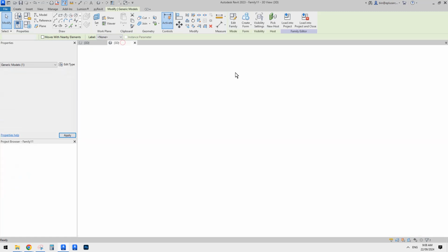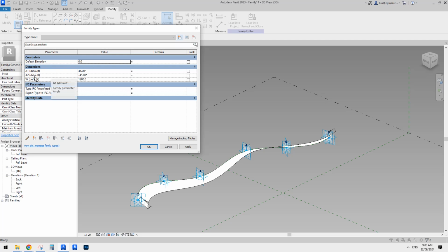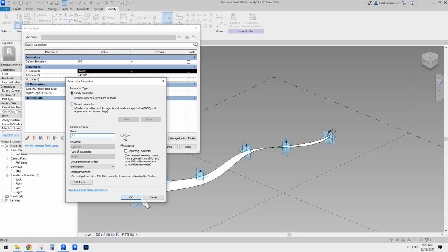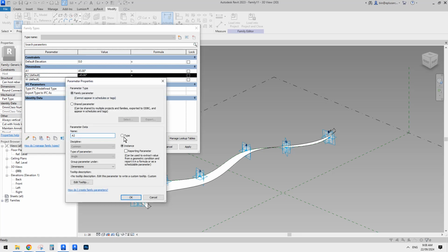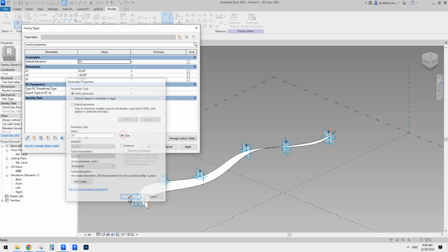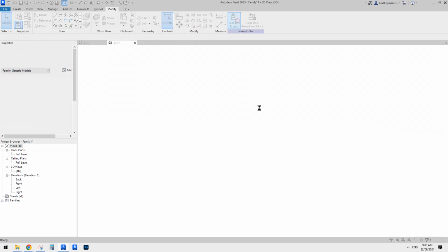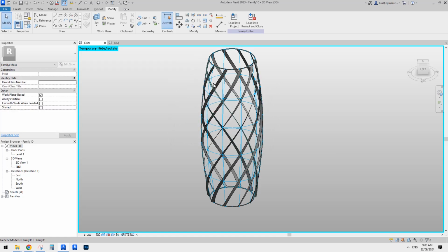1.62366 meter. Okay, so you can go to family types, and see all these with a bracket default. It means they are instance parameters. So you can just simply click on edit, change them to type parameter. Okay, and okay, and load this one and overwrite. So this will overwrite all the previous instance or any change to the instance parameters.